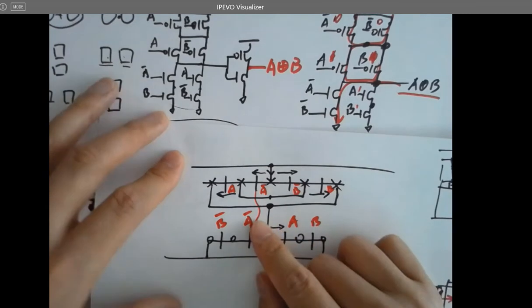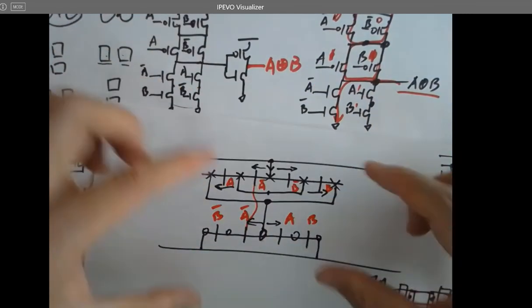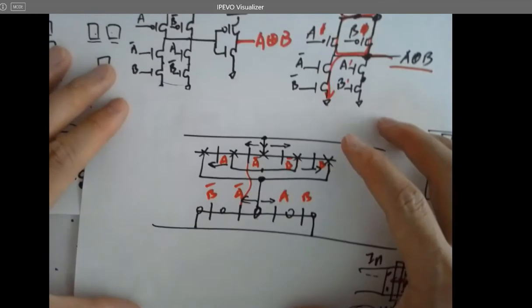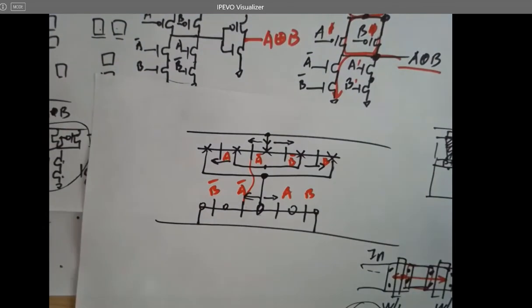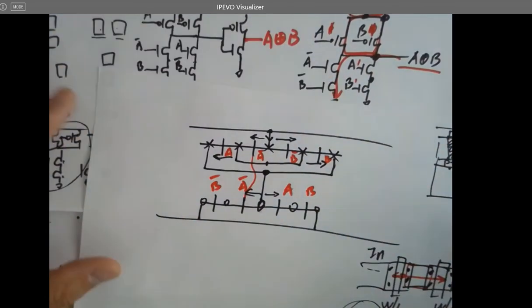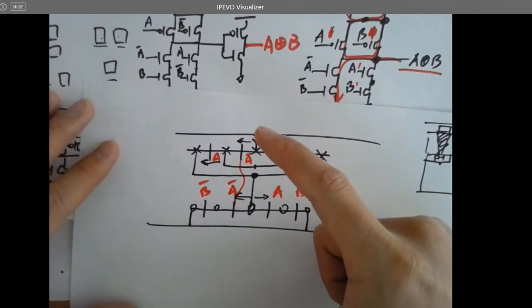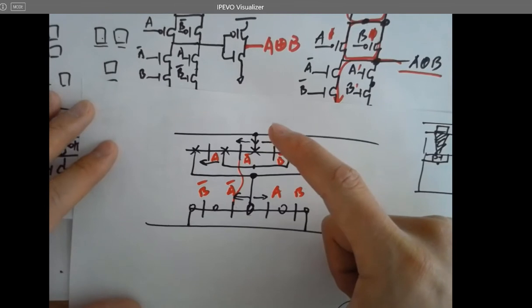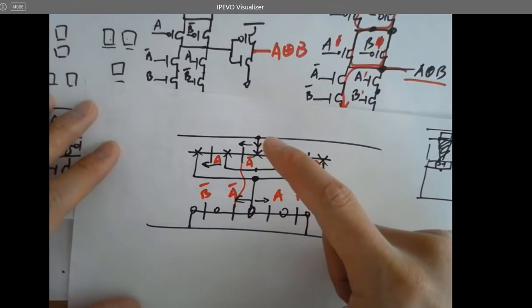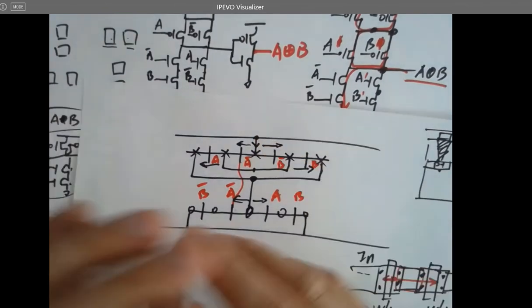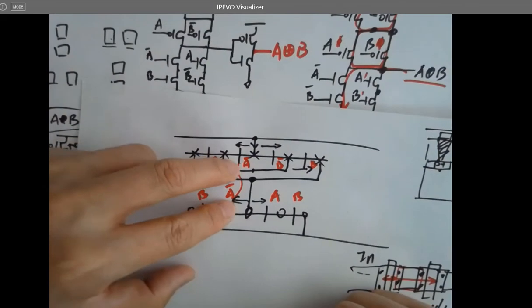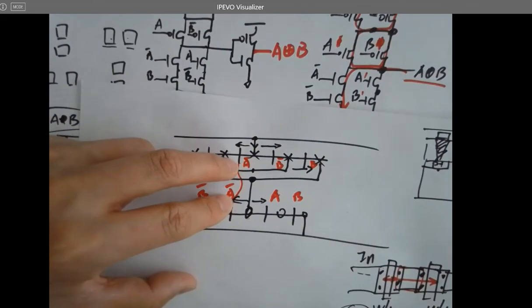However, if you have a really long distance, but for some reason, I don't know, you just design it in that way, can you still draw a super long polysilicon wire? It's not ideal. Unless you have to, right? So if you have a really long distance, you want to connect these two gates together. It's one signal line.